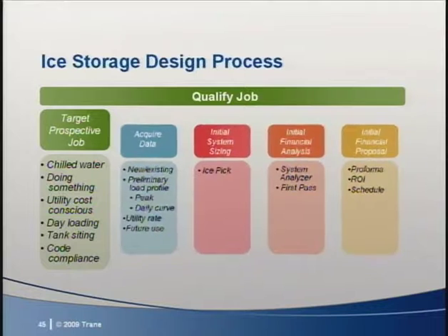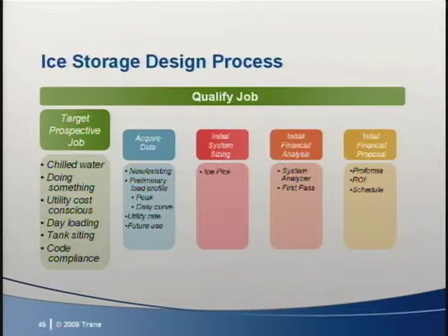Secondly, it's important that the owner plans to spend money on some type of installation. It may be a new building or a chiller changeout. The point is that it makes sense to consider ice storage as an alternate to doing something else, so you have an ROI comparison basis. Having building off time, or at least reduced loads at night, as well as a place to site the ice tanks is also very important.